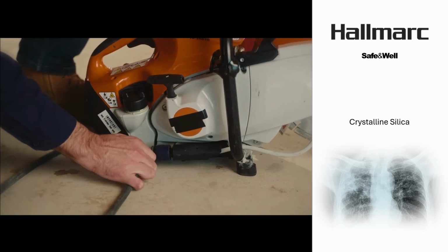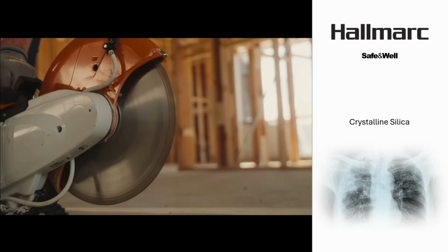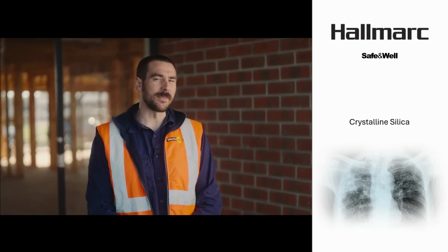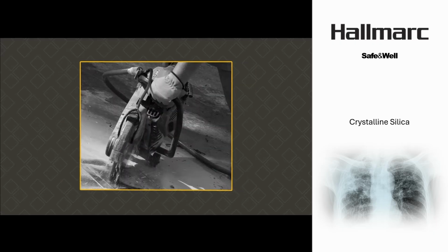The water supply needs to be directed at the point of contact, and the flow rate needs to be high enough to suppress the dust. This is usually around half a litre a minute. Any overspray needs to be pointed away from you or anyone else.